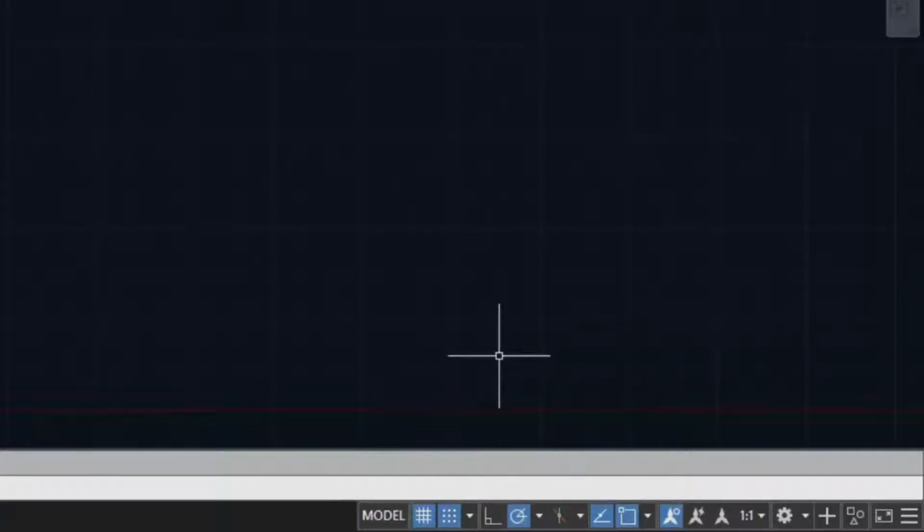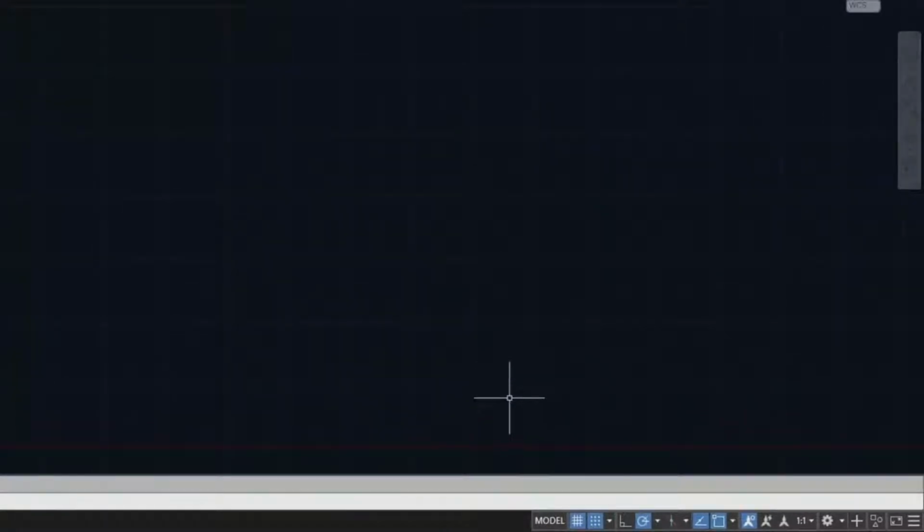Now there are two nasty ones on there that are good for professional draftspeople because it saves them having to do things. It's an intuitive thing. It's called Dynamic Input and Dynamic UCS. They help a drafter if they forget to do the mundane things like put an @ sign in when they're supposed to, and it does it for you.